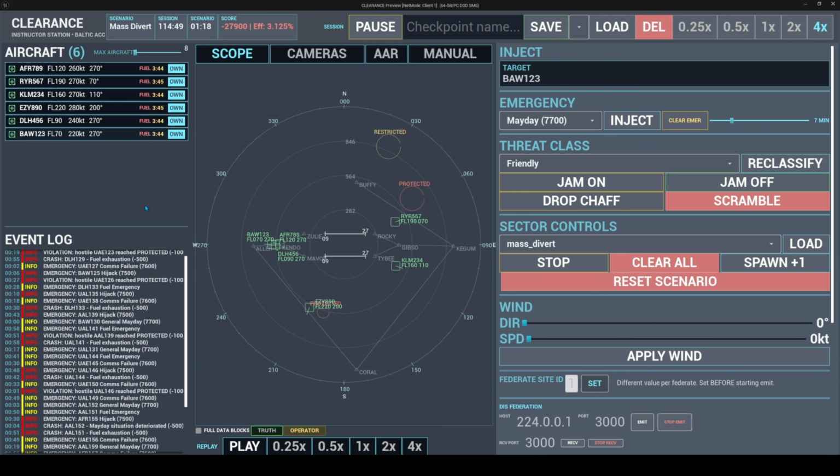The console goes into the simulation controller, which pushes the target heading to the aircraft's behavior object. The wrapper computes the heading error, commands a target bank, feeds the flight command into the model, and the aileron comes back out and the aircraft banks.